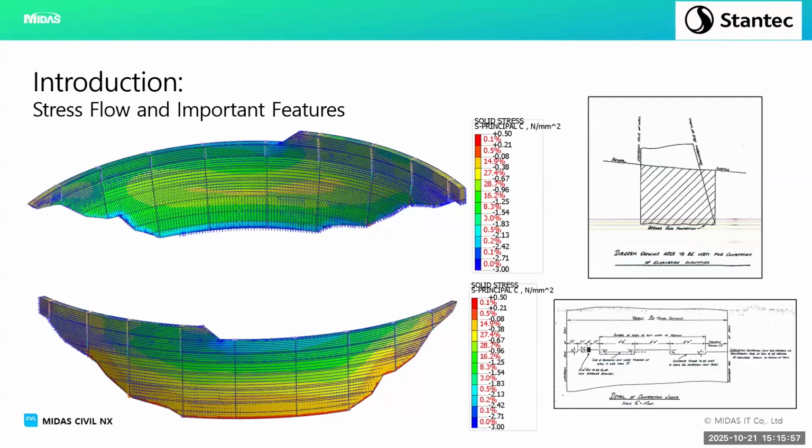A key point to the construction here, and it's actually quite common in the older dams, arches thin to thin-medium, is the keying, the pocketing. On others, there are actually discrete shear keys that they put in there. And that's why one of the biggest things on an arch is to try and ensure you don't undermine or deteriorate the downstream foundation of the center monolith.